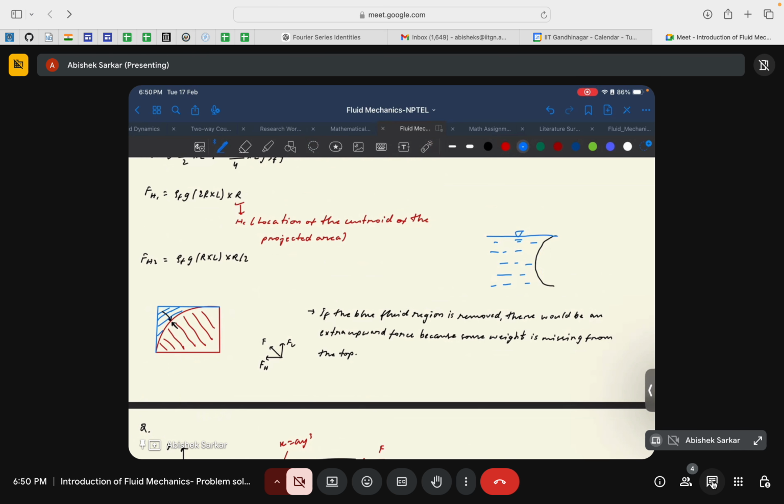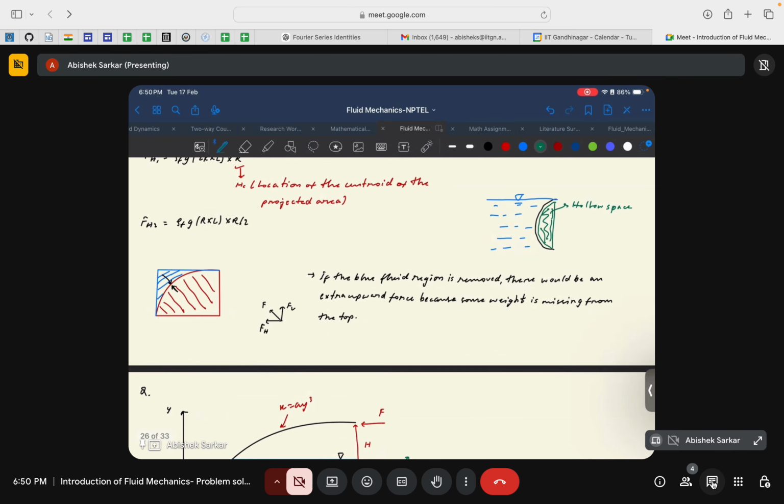So you will find it the same way. We use a different color. Assume that this is the amount of fluid that is being held in this hollow cylinder. The evaluation for the net force that acts on this curved surface will be exactly the same. So Fv would be pi r square L by 2 times rho F g.